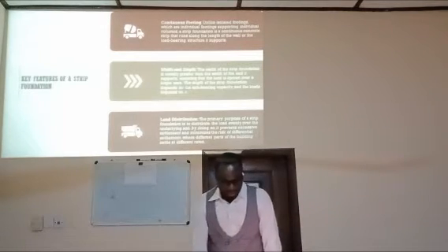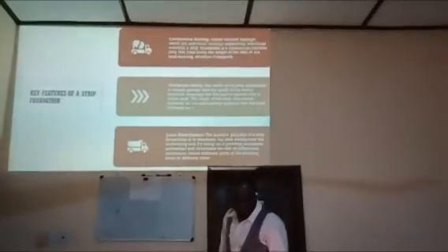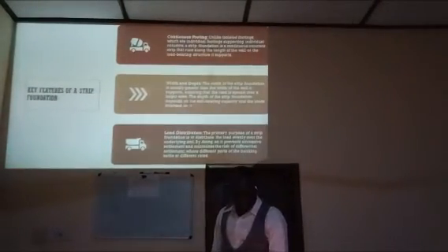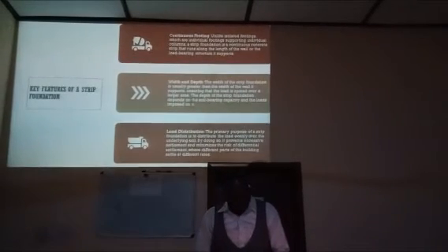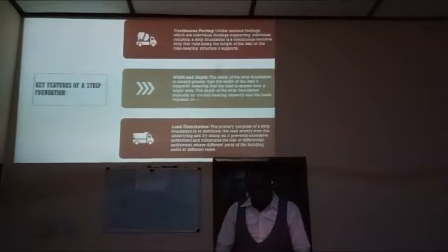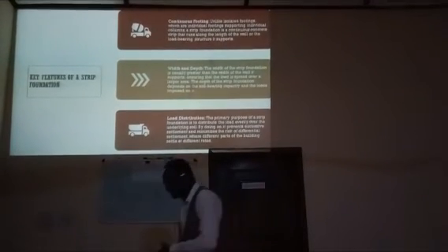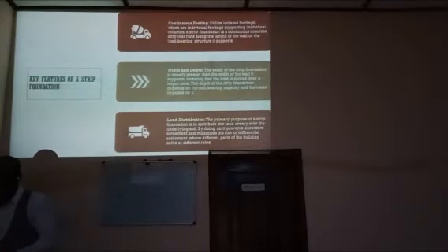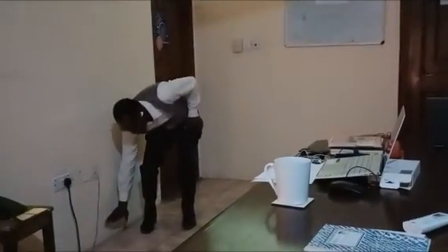Now, the width of the foundation is bigger than the width of the wall. You will discover somewhere here where the foundation is that you see there is a protruding part. The concrete width is larger than the width of the normal wall. So if you are using, for example, a 9 inch, or what we call a 225 block wall, the footing might be 600 running across.